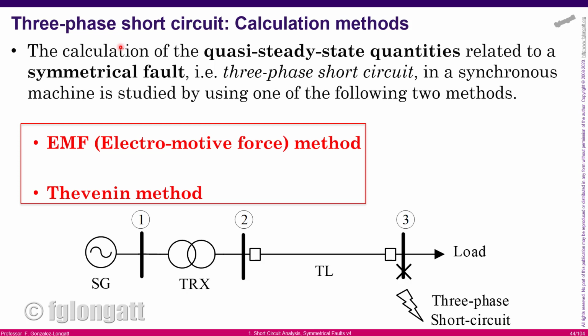However, it will take more time and require more data in order to perform calculations. On the other hand, Thevenin has been a very successful tool for circuit analysis. Now we can use Thevenin theorem for short circuit calculations, okay?